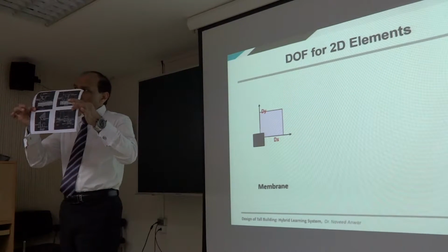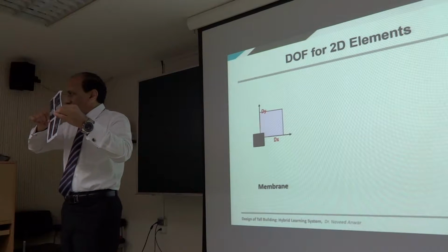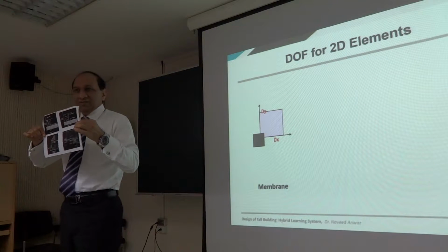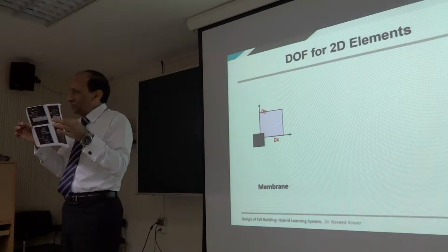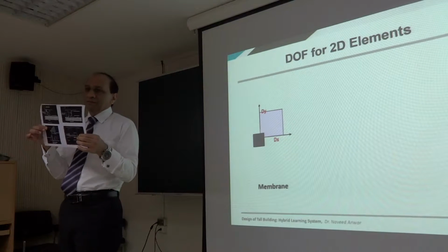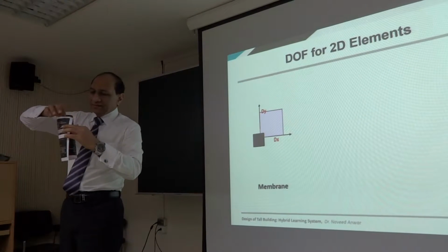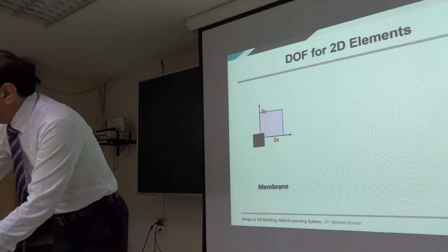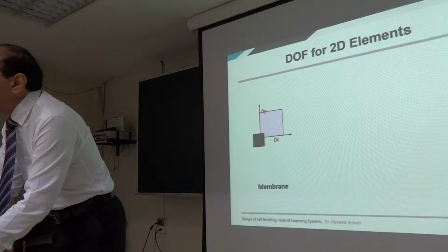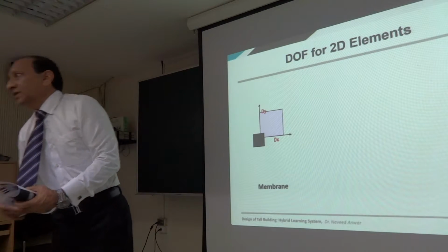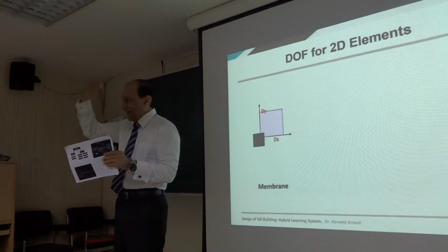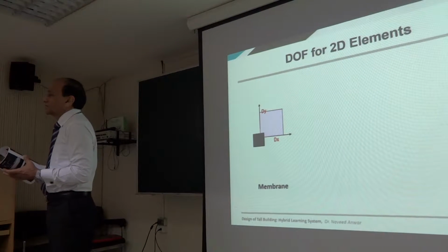In plane means if you apply the forces in the plane of the object, it will be quite strong. Mostly in tension, because as soon as you apply compression, it will buckle, right? It will just go away. Mostly in tension, but can also be in compression. But if I fold it like this, I can now put my cell phone on it, it will be fine, right? So same membrane, which is very, very weak in getting any forces, if I form it in the right way, in such a way that all the stresses are within the plane, it can become a very strong structure.